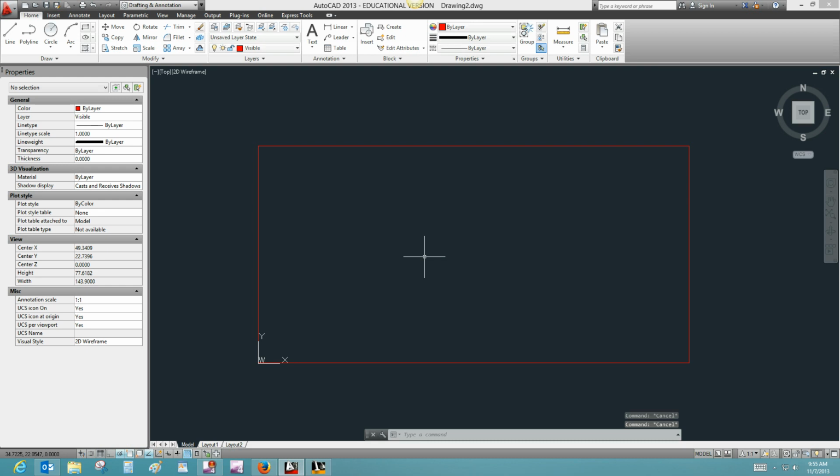Okay, so let's start off with the A diameter circle. The hole A has a diameter of 7. There's only one of those on our drawing, and it's an absolute coordinate 64, 38. So 64, 38 will be the center point of our circle with a diameter of 7. So that is our first circle.